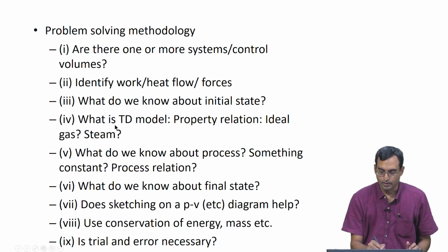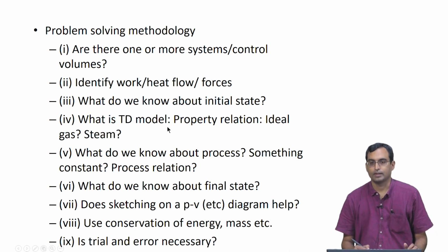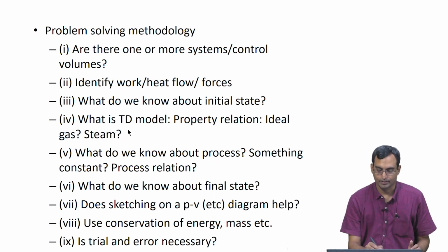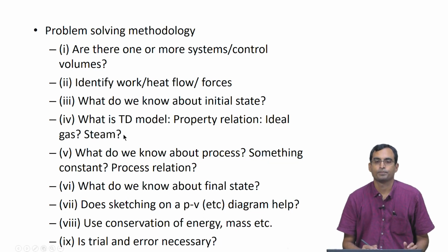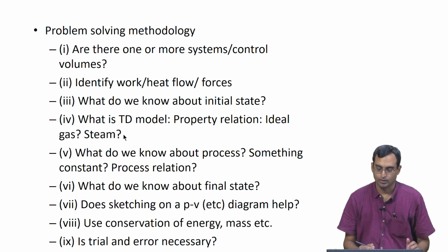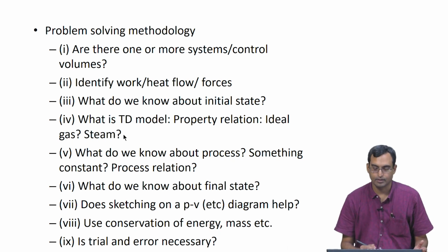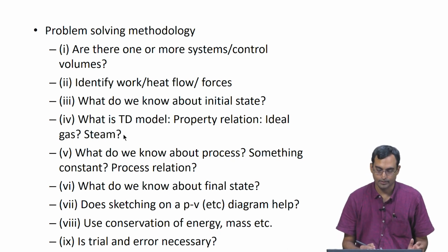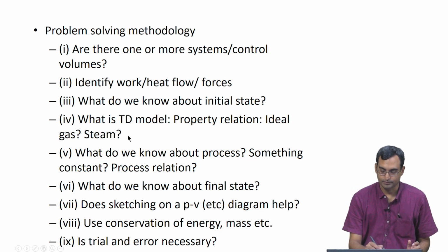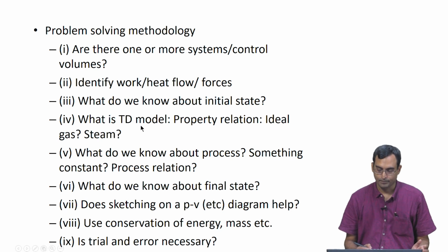We will look at what is the thermodynamic model, which tells us something about the property relations. Is it an ideal gas where we have a relation PV equals mRT? Is it something like steam, where we can use tables, which we will look at a little later on? Is it a real gas where we can use other relations or the compressibility charts? This is something which we will decide. Once we know this, then we know how to calculate properties.